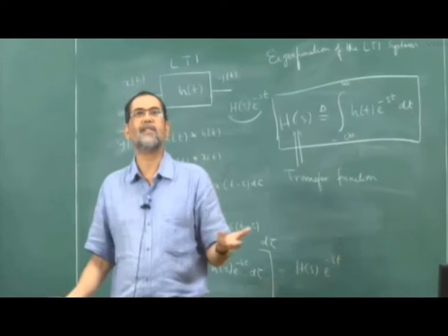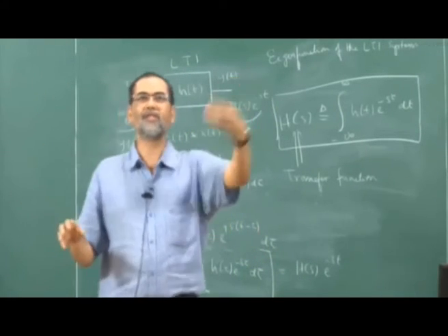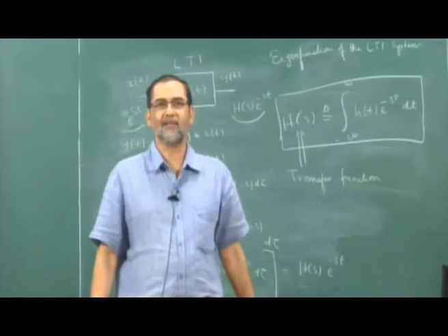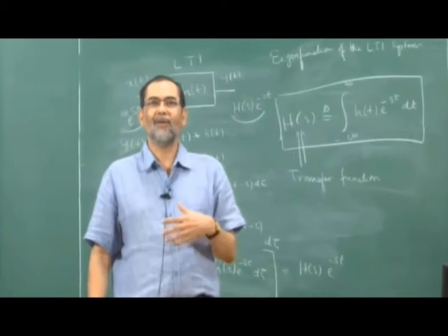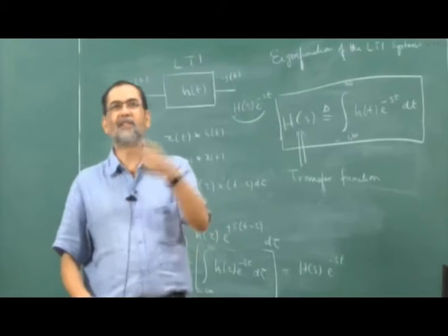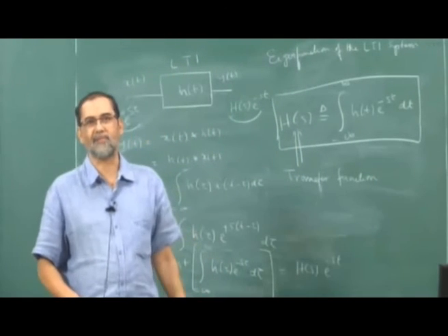At the output, it is DC, that is 0 hertz. So frequency is destroyed. Input frequency is 50 hertz, output frequency is 0 hertz. So that is not an LTI system. So when I said you are surrounded by LTI systems, here is an example: wherever the frequencies change, they are not LTI systems.